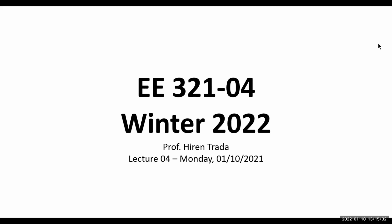Let me see. I think we stopped here, right? Characteristics of VI and IV characteristics. Of course, forward bias and reverse bias regions we talked about. This right here is the threshold voltage. That is a small amount of voltage required to turn the diode on, meaning from that point on, the diode will actually be conducting current. In the reverse side, we are connecting a negative voltage, or the cathode is at a lower potential than the anode, then it's reverse bias. Only a very small amount of saturation current would flow through.